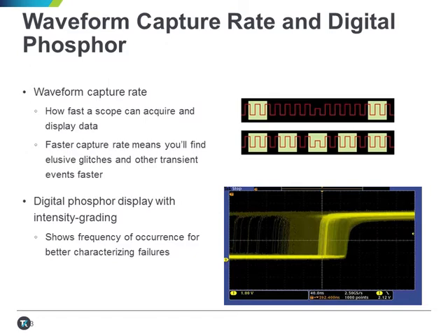And you'll find it on Tektronix scopes from our basic bench models to our higher performance lab instruments. The lower picture on the slide shows how a digital signal varies in time relative to the trigger, which is on the left-hand side of the screen. You can see by the intensity that the rising edge spends most of its time in the center of the screen, but moves over about 4 divisions. And occasionally the edge happens even sooner.